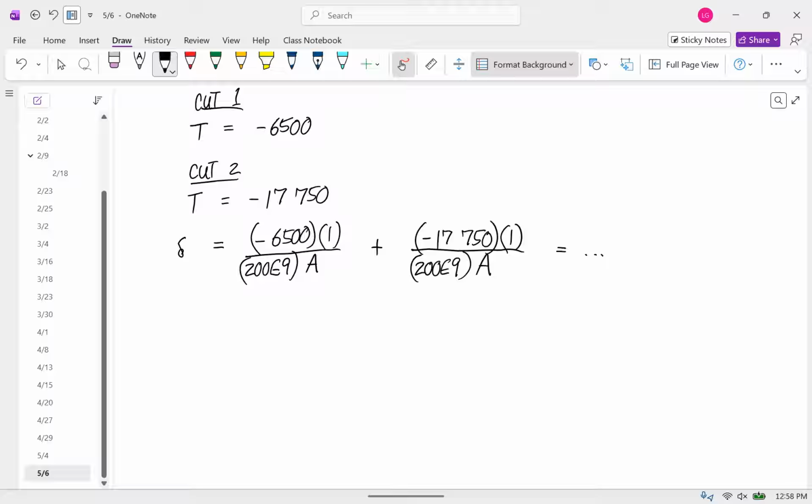And so you could punch in different values of the area and see what the values would be. Or one thing you could do, we did a lot of this kind of stuff with spherical and cylindrical pressure vessels. I could say, okay, we want the elongation to stay less than this or whatever. What cross-sectional area is the minimum that we could use here?